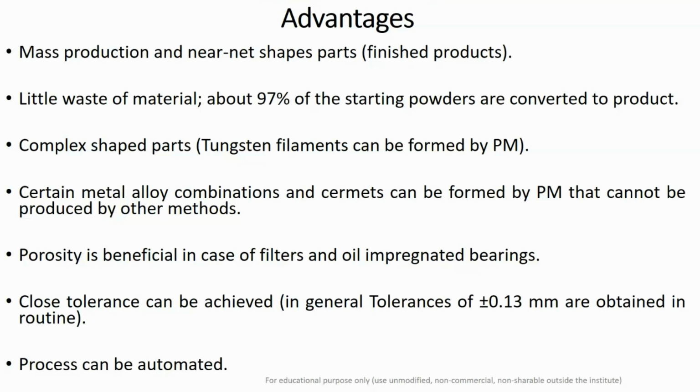Porosity is beneficial, first of all, in making filters. You all know that filters are porous, and due to the specific porosity, pore size and distribution, or configuration, you are able to filter out your desirable fluids. Another application is the oil impregnated bearings. These are a very special type of bearings in which we intentionally create porosity.